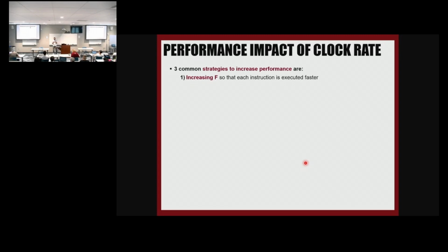If we increase the clock frequency to 10 gigahertz, it means that your task should be finished in 100 picoseconds. Otherwise, you mess up your system. You keep sending commands and you don't wait for it to finish. That's what it means. If I don't have a fast enough adder and I clock it at 10 gigahertz, I don't give it enough time to give me the result of the add.